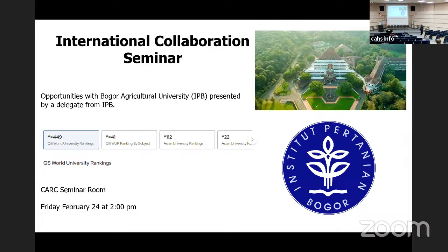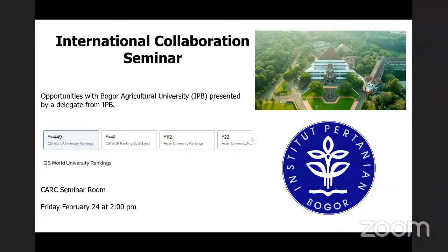It means if we go one vertical, you go 3 horizontal. So if it's a 1:1 slope, that means 1 horizontal, 1 vertical. It's a steep slope, and they cannot do it. It's not recommended by the federal rules and also the state and other counties. Even if numerically you put in a high strength parameter and the soil is very good, the factor of safety based on the numerical simulation is more than 1.5, but it's not allowed at all. So typically it's 1:3, but sometimes 1:2.25 or 1:2.5, because we need space for the frontage area. So we need to cut the slope and make the slope steeper.